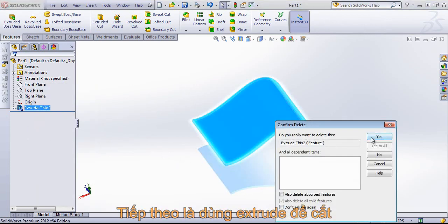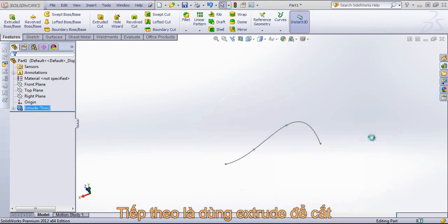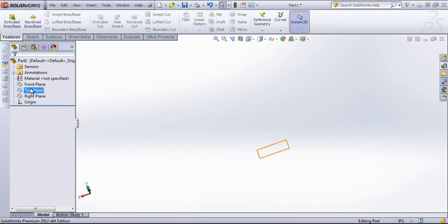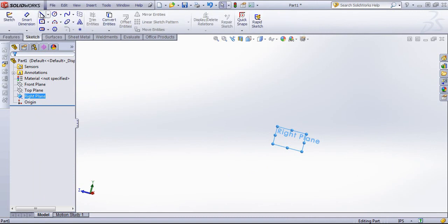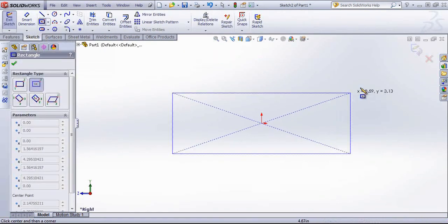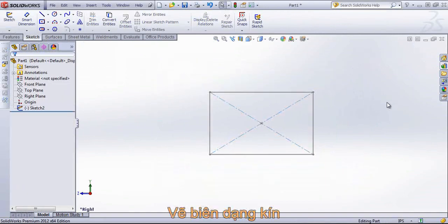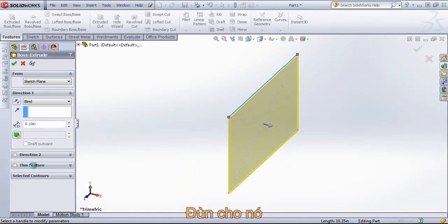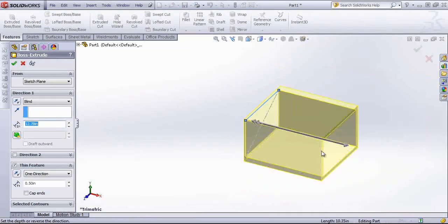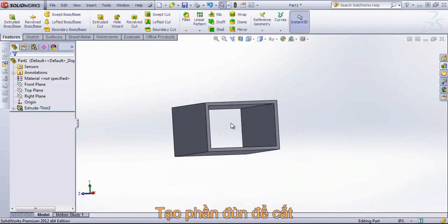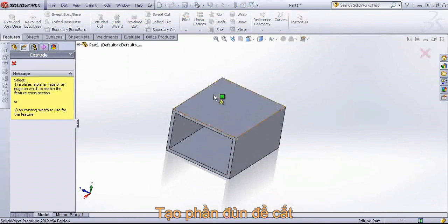Lastly, I can also create cuts using the extruded thin, and I can also create extruded thins from closed profiles. So if I create a new sketch, and use a closed profile and create an extrusion, I can choose that thin feature and have this shelled out part.